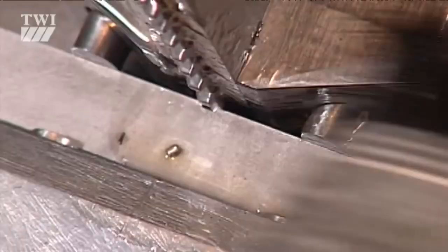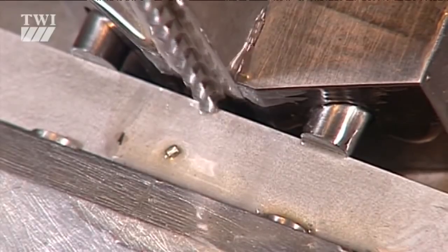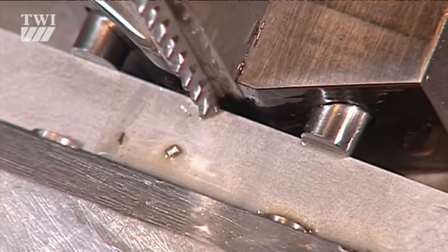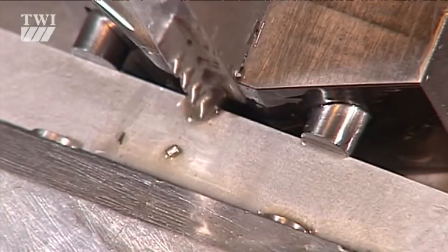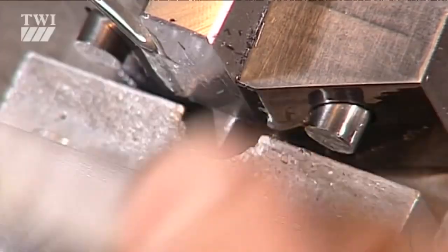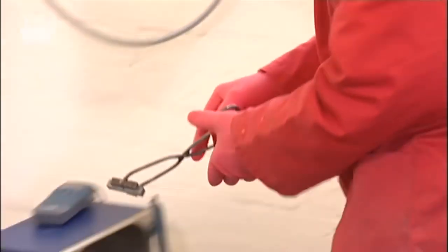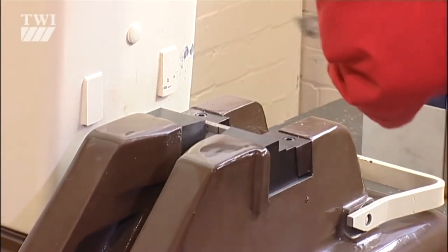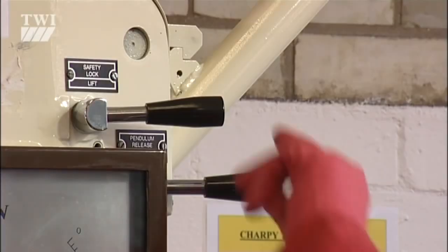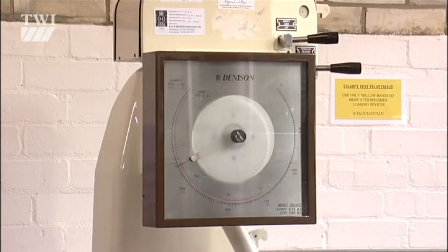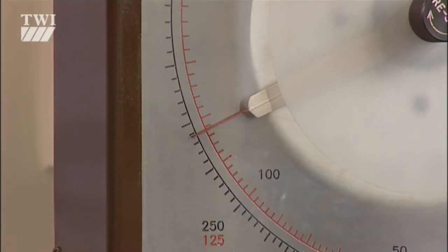Only a little material is required for each specimen. They're 55 mm long, 10 mm square, and have a 2 mm deep notch, but can be smaller for thin materials. The specimen is struck on the opposite face to the notch. It's fractured, and the pendulum swings through by a specific amount, giving a measure of the energy required to break